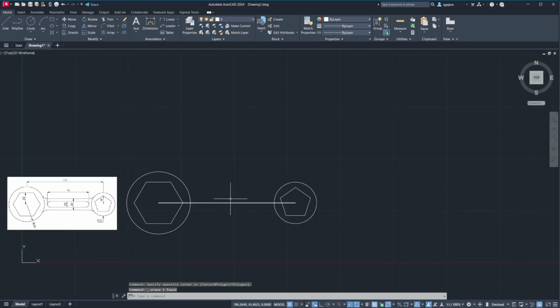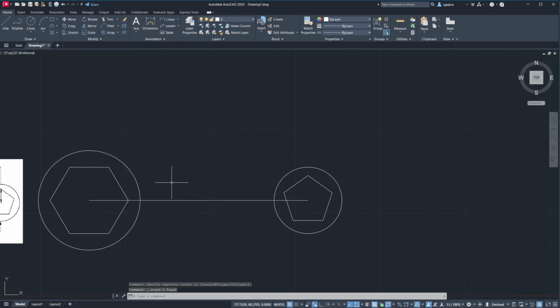So, that's redraw. Again, let's do a rectangle. If we do a rectangle, we press R. R is redraw. If we press E, E is regen. Actually, I don't know what regen does, I think I've never used this tool. But rectangle is REC. Again, you can always access a tool as long as you know the name of the tool. So, REC. We'll just start from here.